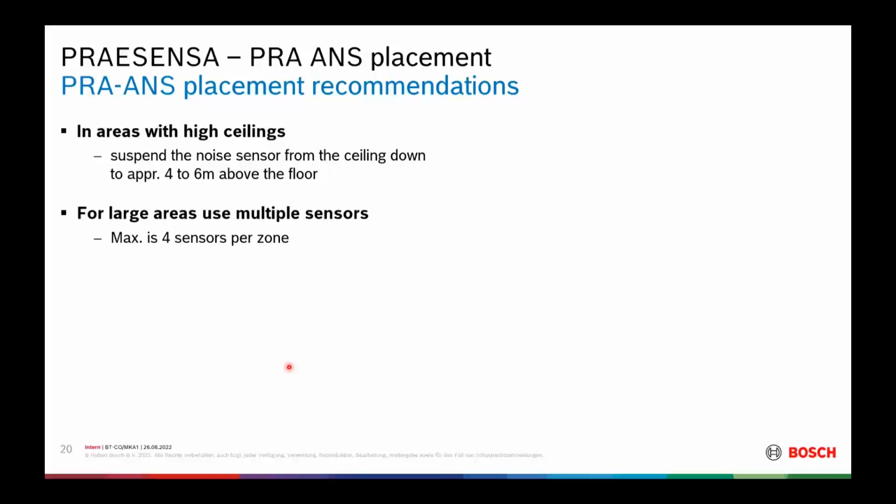Is it distributed noise sources? Again, airport terminal, for example, gate area. The biggest noise source there might be people chatting with each other, creating noise by going around with their baggage trolleys or whatever. Those will be all over the place. So you will have a large distributed noise source, which is maybe affecting your background noise level here.